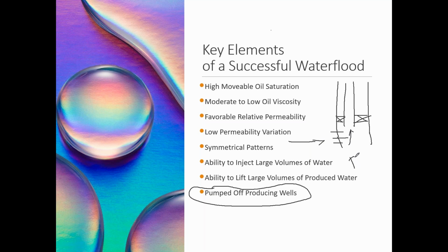Your pressure is increasing and your fluid inside this particular wellbore is being lifted to the surface without doing any intervention jobs. But what might happen if the volume of water or the water cut goes as high as 90 to 95%? The reservoir pressure might not be sufficient to lift this fluid.